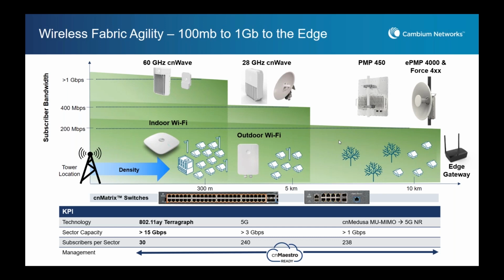Well, okay. As you know, this product has a wide coverage of 280 degrees. That said, you can actually overlap these. The adjacent channel interference is such that you can actually have them on adjacent channels. If you are going to put them on the same tower, I certainly would advise that. So 4 of them on a tower will be possible.